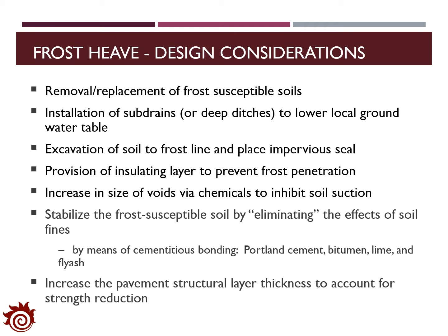Also, installing the sub-drainage system to lower the local groundwater table is an efficient method. With a lower local groundwater table, we are able to prevent the capillary rising effect so that we can maintain a certain amount of the moisture contents. Excavation of the soil to frost line and placing an impervious seal, and the provision of insulating layers to prevent the frost penetration can also be very effective to prevent the frost heave. We are also able to increase the size of the void to inhibit the soil suction so that we can reduce the impact of the capillary rising effect.